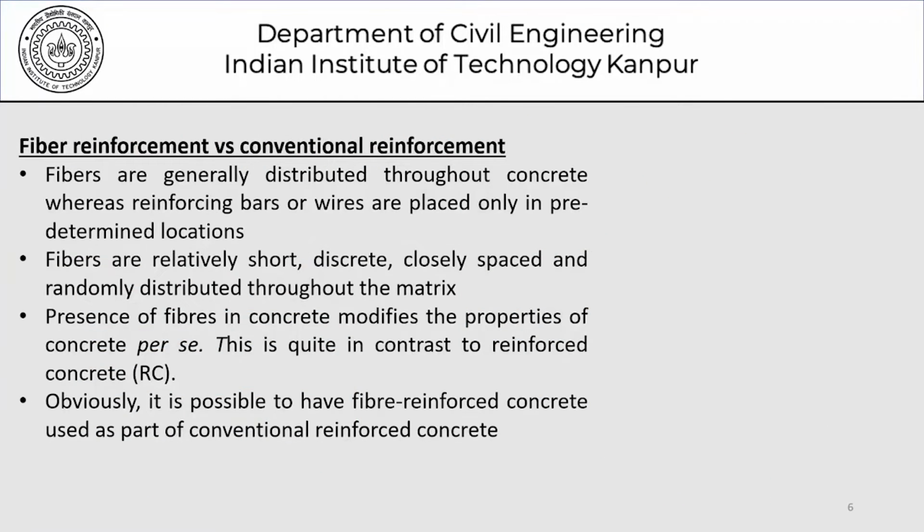Fiber reinforcement versus conventional reinforcement. Now that's something which often comes to our mind, that okay, how is fiber reinforcement different from conventional reinforcement? We know from our discussion of reinforced concrete members that if we have a beam which is simply supported, let's say, and we subject it to a loading here, this portion of the beam will develop flexural stresses in excess of the tensile strength of concrete, and we will have flexural cracks.